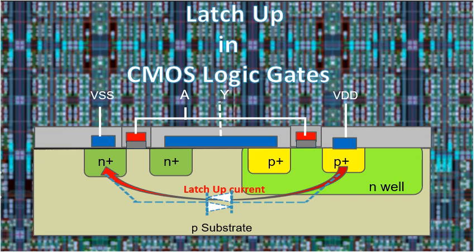Welcome to this video on latch-up phenomenon in CMOS logic gate structure. A latch is a bistable switch that operates as open in off state and a short in the on state. A CMOS gate structure has a built-in shunt parasitic latch. Breakdown of the undesirable latch leads to logic gate burnout, and this phenomenon is known as latch-up. In this video, we will identify CMOS structural parasitics, latch structure, breakdown, and its prevention methods.